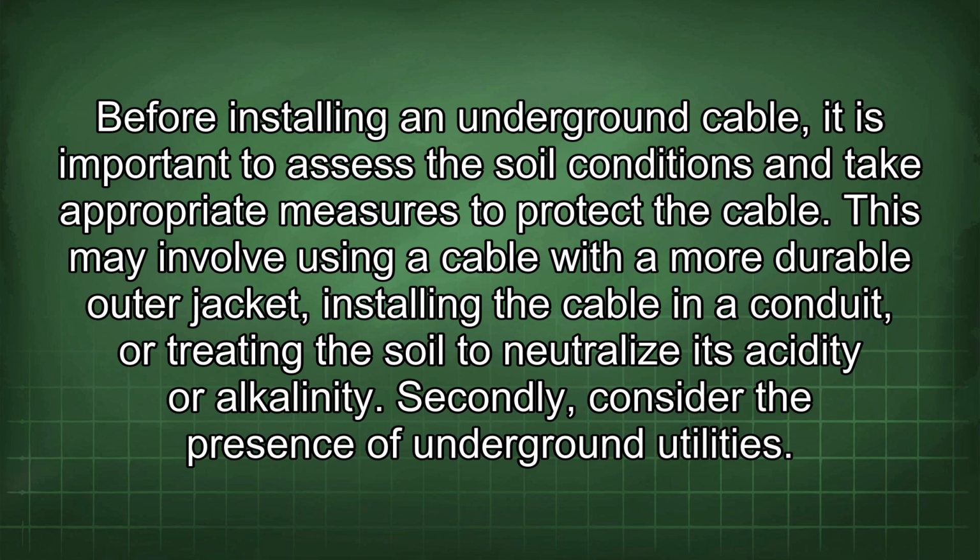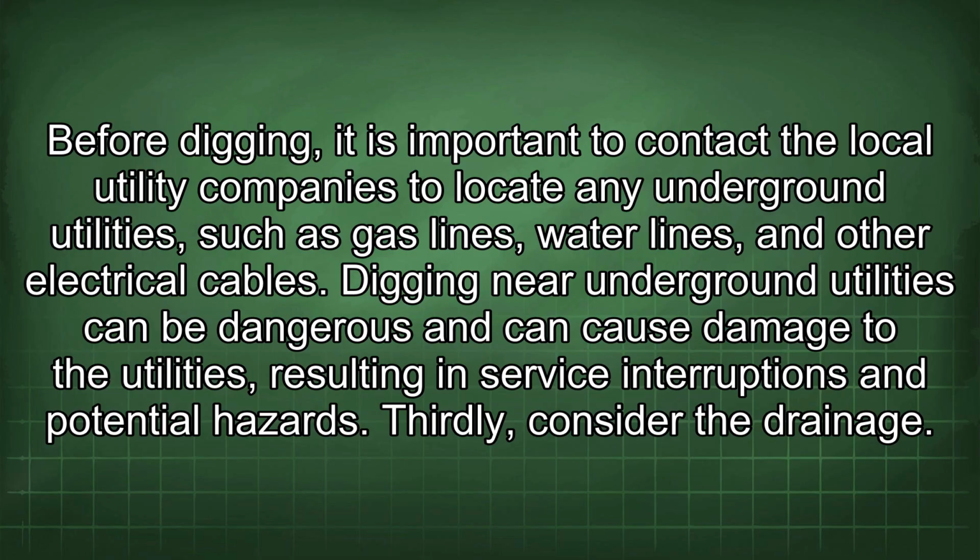Secondly, consider the presence of underground utilities. Before digging, it is important to contact the local utility companies to locate any underground utilities such as gas lines, water lines, and other electrical cables. Digging near underground utilities can be dangerous and can cause damage to the utilities, resulting in service interruptions and potential hazards.